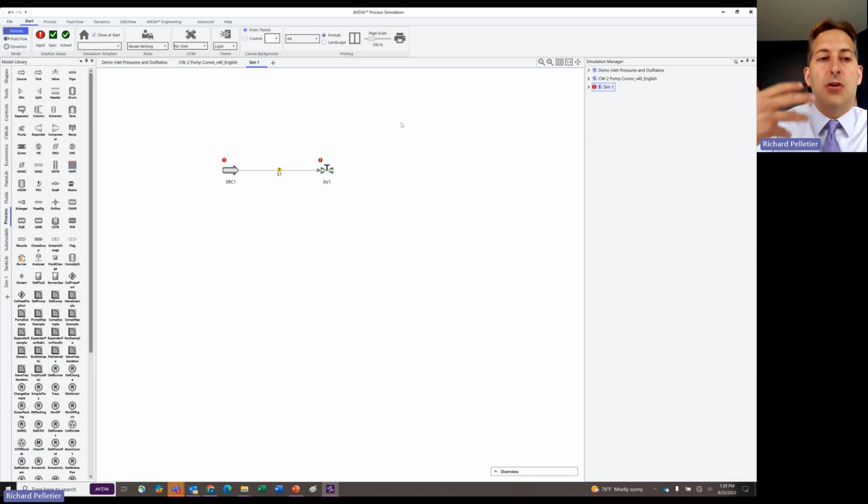And that's really the whole purpose of the connection model, is that you don't want all these miscellaneous models that are used in a redundant way for just property calculations, or you have like 100 pipes in a simulation. You don't want them all over the canvas because it's going to look very cluttered and it's going to be very hard to navigate, right? And so we use these connection models to declutter the canvas and make it so that the information is embedded into the connection itself.